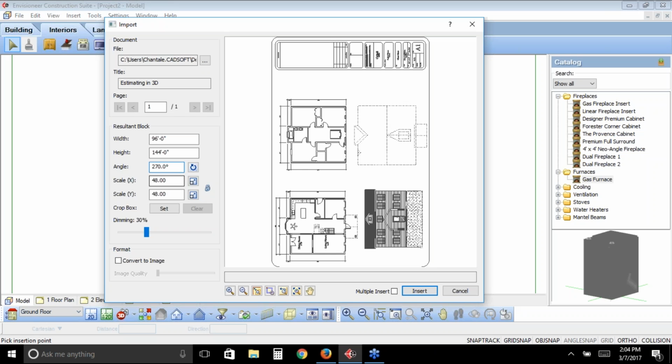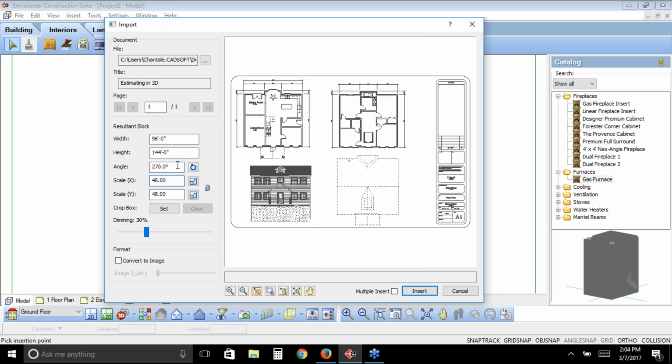If you don't know the angle, then you can always use this pick the angle. So say you've been brought a PDF and it's on a really obscure angle. Maybe it is one that they did trace over top of, and it was a raster image, and they scanned it. You can always pick the angle as well to kind of straighten that out too.